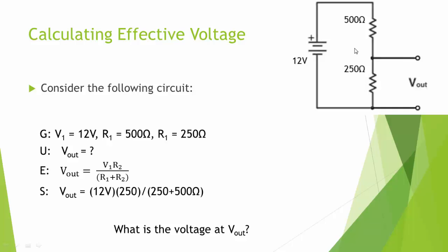By my count, it should be about 1/3 of the overall voltage, and in fact it is 4 volts. So we can essentially get any voltage between 0 volts and our power supply maximum voltage using a voltage divider. The only catch here is we want to make sure it's a low current device, for reasons we won't get into.